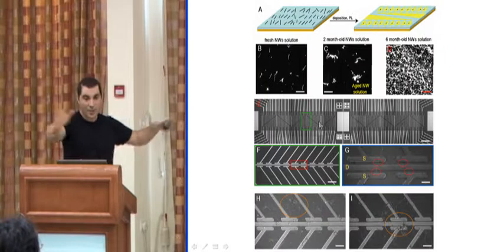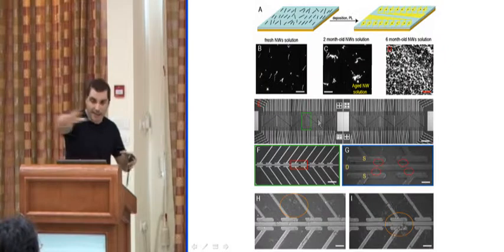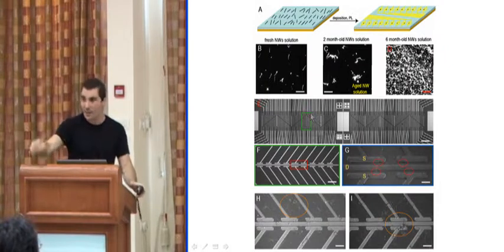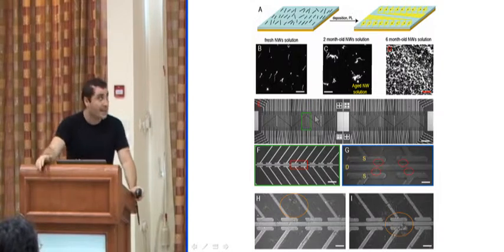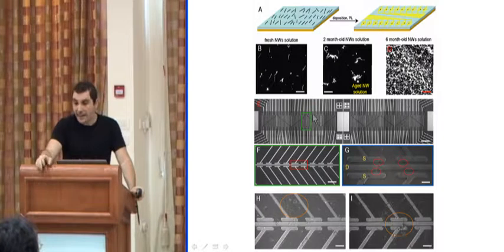Then we wash all the photoresist around, and we get nanowires just inside the windows. So then, by using those novel techniques, we can get that every one of the devices will have at least one nanowire in between the electrodes.